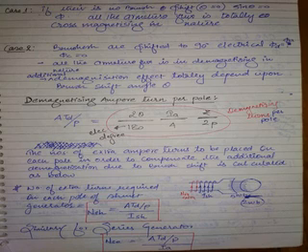So what happens to the voltage in the machine? So what you have to do now? You cannot eliminate this demagnetizing effect. If you do brush shift, it will come. So if you want to compensate this demagnetizing effect, you have to add some extra turns and produce exactly equal to the demagnetizing effect. Don't produce more or less. If there is 2 Webers demagnetizing flux, add exactly some turns which produce exactly 2 Webers. So you produce 7 Webers out of the pole. In an event of brush shift, if there exists any 2 Webers, it will compensate. And what's the net flux coming out? 5 Webers, and you will get the net voltage.